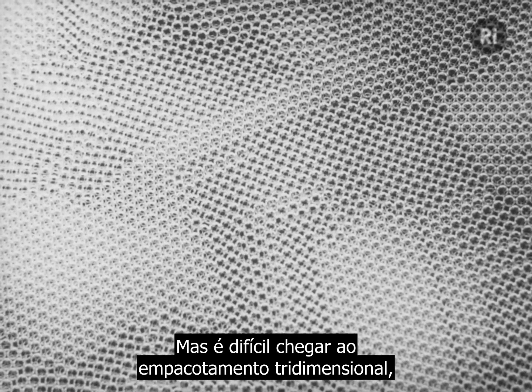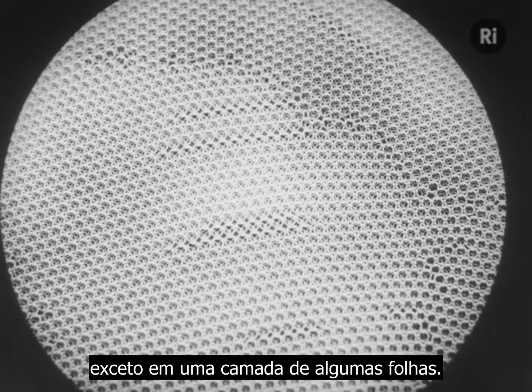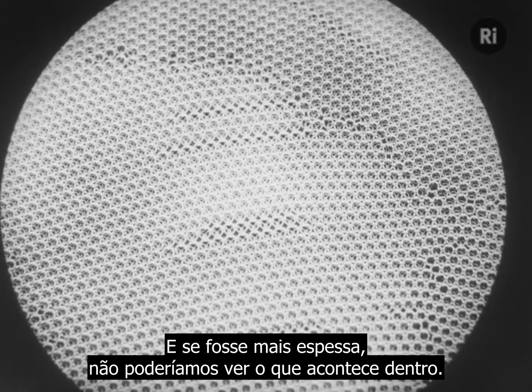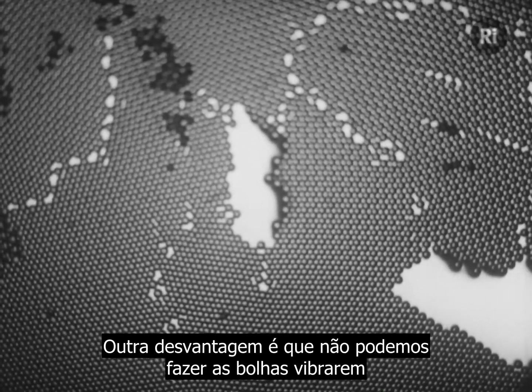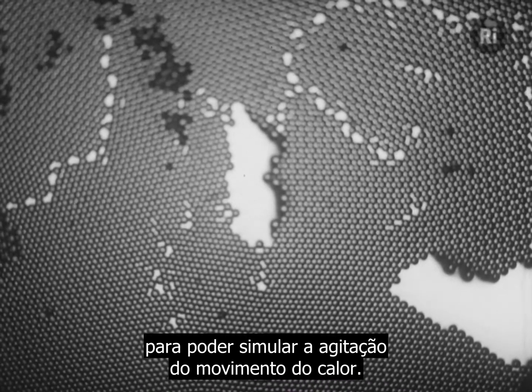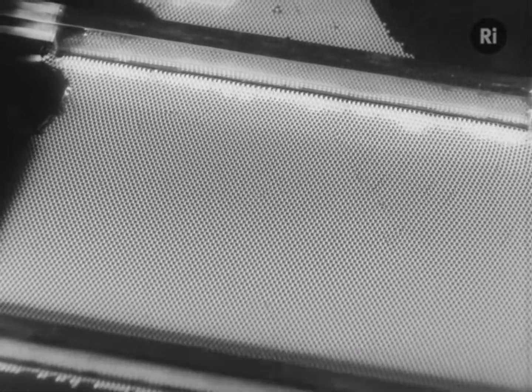But the three-dimensional packing is hard to obtain except in a layer of a few sheets, and even if it were thicker, one could not see what happens inside. Another disadvantage is that one cannot set the bubbles in vibration and so simulate the agitation of heat motion. Nevertheless, the model suggests many ideas, and when we see the dislocations dashing about, we can form a mental picture of what is happening in the metal itself.